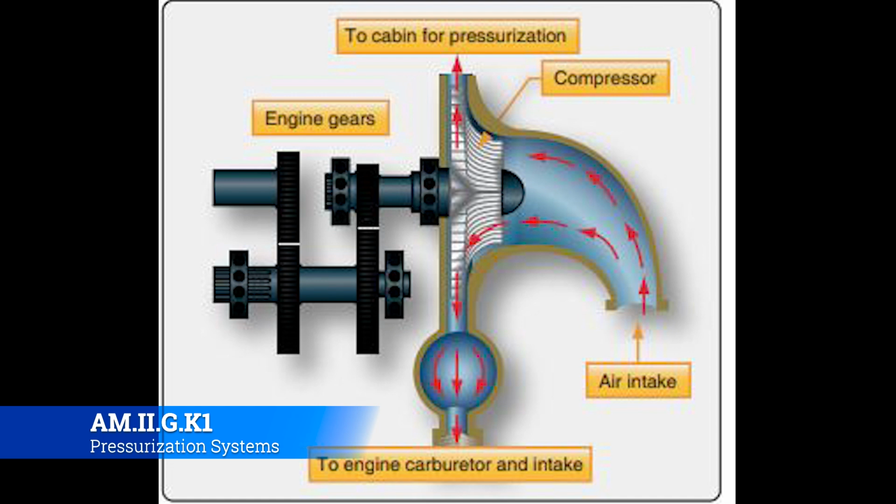Now, whenever you inspect those turbos and superchargers and air compressors, they're all going to have their own inspection criteria that makes doing the annual on the plane a little bit longer and a little bit more involved, and it is frequently a source of airworthiness directives. So that's something you're going to want to pay attention to. They all have to be lubricated and taken care of in their own time, and you have to be very conscious of inspecting them specifically for exhaust leaks, because they're just known to have them.